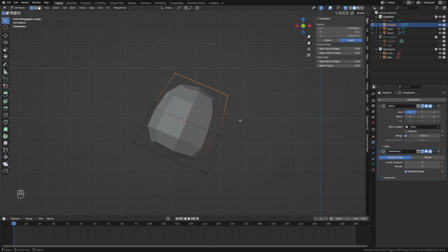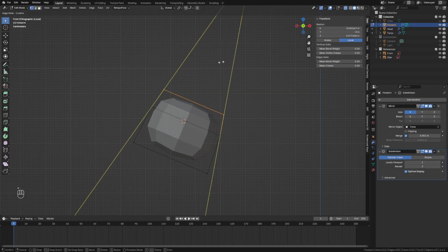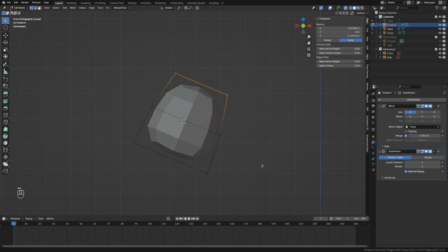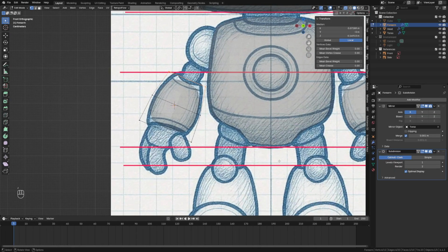If I press G twice, you see the edge loop that follows the yellow line. If I want to slide in that direction, it won't let me. But I can press C to toggle clamp off. The guide extends and I can slide in that direction. This side sliding edge loop won't help much.